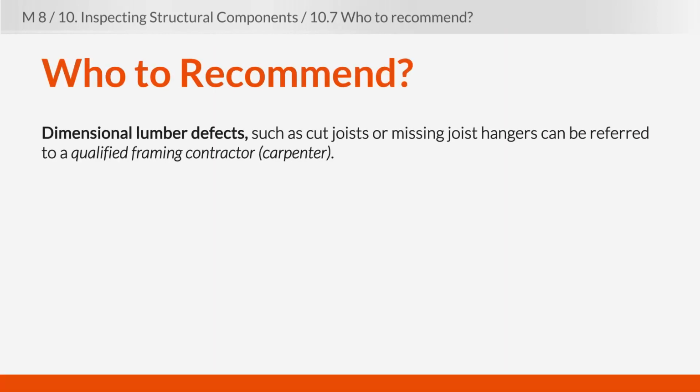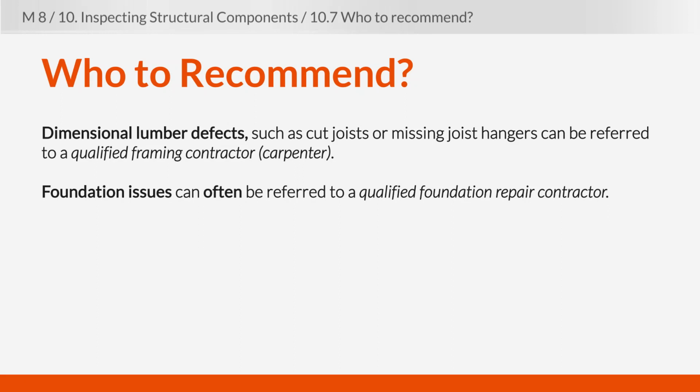As a reminder on who you should be recommending, defects with dimensional lumber, such as cut solid wood joists or missing joist hangers, you can recommend further evaluation by a qualified framing contractor, which is just a fancy way of saying carpenter. Foundation issues, and we haven't talked too much about this, but foundation issues can often be referred to a qualified foundation repair contractor.